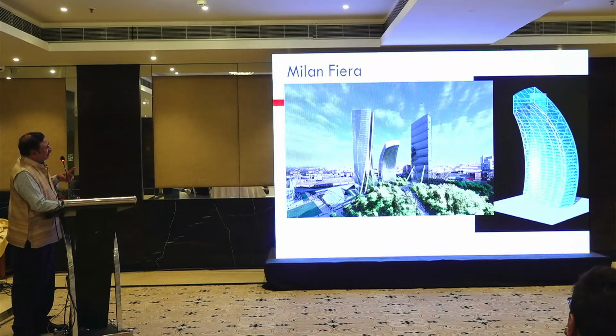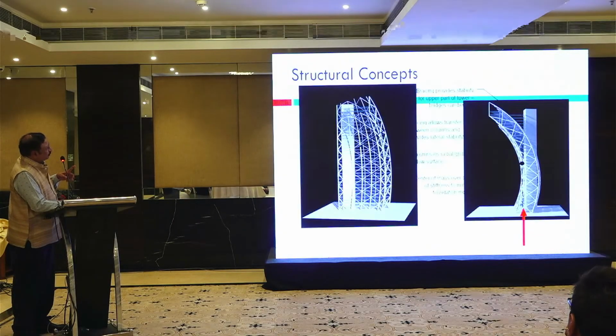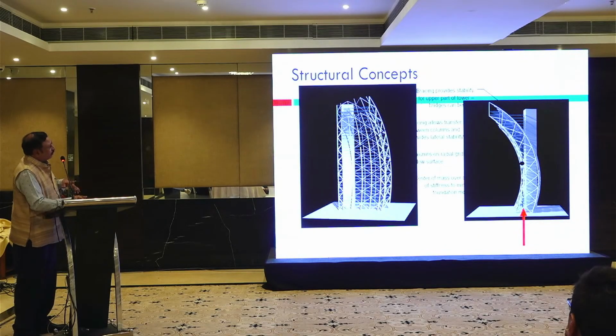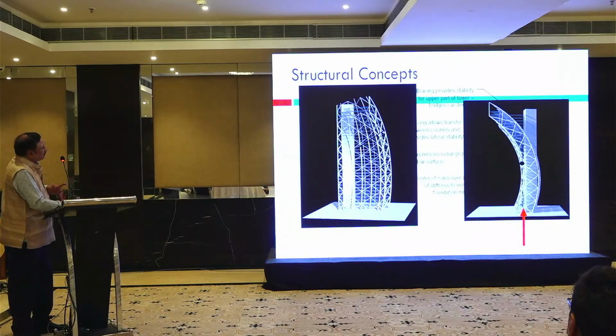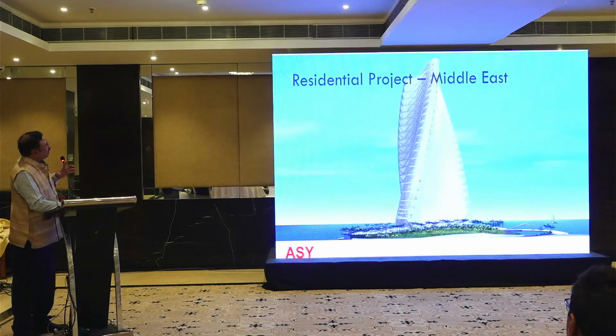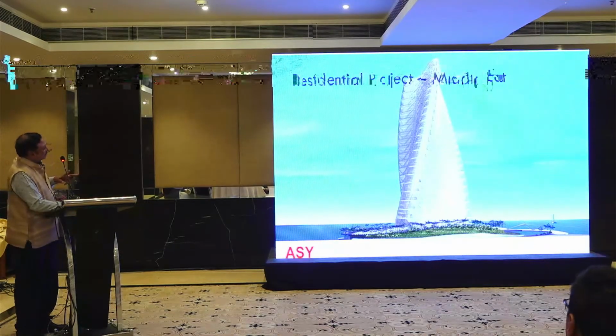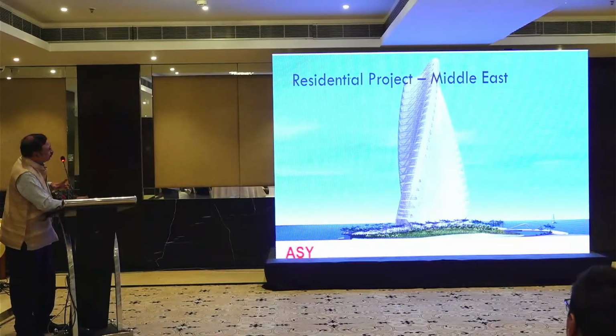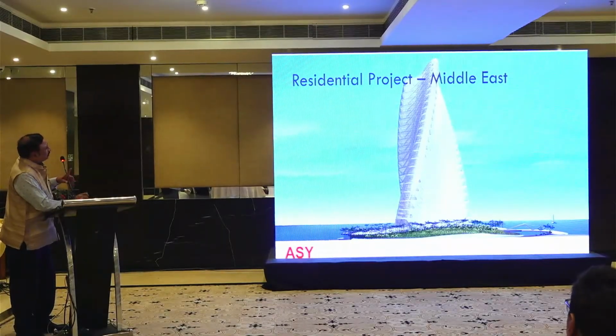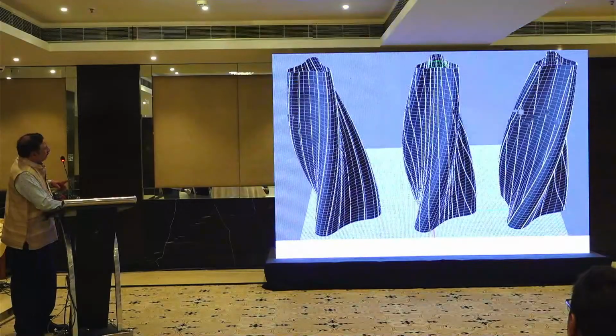This is how the bracing has been done. And interestingly, if you see the mode shapes, the bracing provides stability in the upper part, and then the lower part is using concrete to improve the stiffness. Unfortunately, the figure is covering the text. So using simple structural concepts, you can arrive at it. And this is in the Middle East, you can see this. The building has been twisted with external bracing to reduce the drift. And these are the mode shapes.